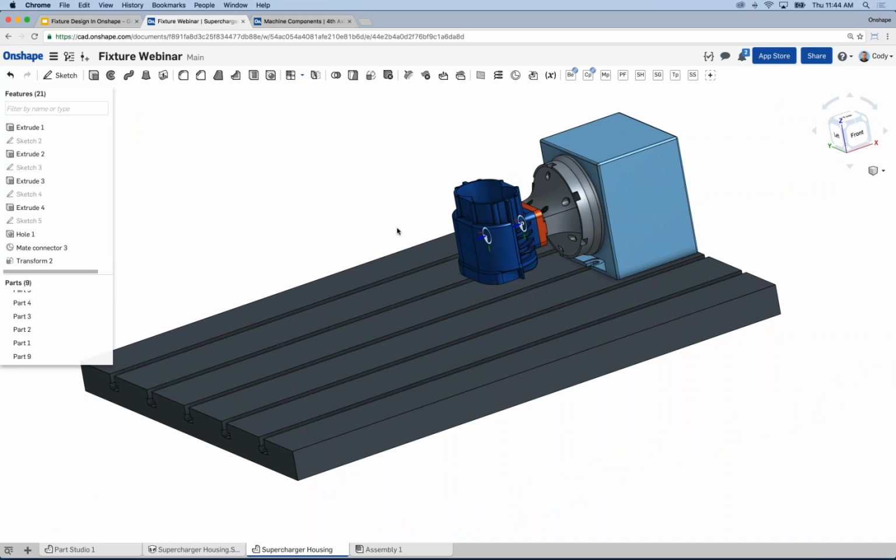Now, if you've modeled it in Onshape, chances are this isn't going to be necessary. It's going to come in the same orientation you modeled it, and if you're designing it that way, you're thinking ahead. But if you're getting the model from some vendor or some other person, this is going to be an important step: exporting relative to a certain position. So that final step, transform with mate connectors.